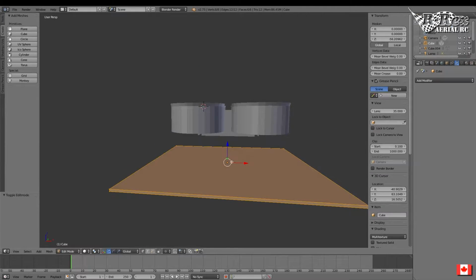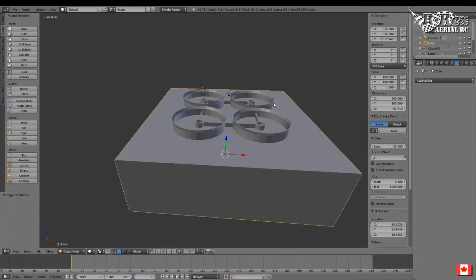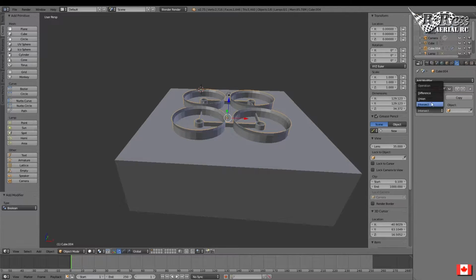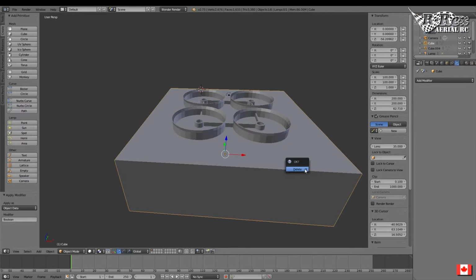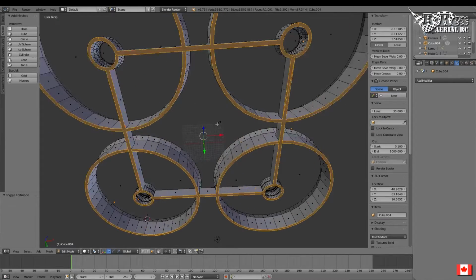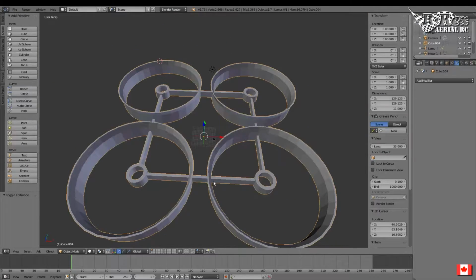Go into tab mode. Select the upper face. And I'm going to put that face to 5.5. There. You notice it consumes quite a bit of the object. So now I select the object, Boolean, difference, and select the cube, apply, and we can delete this cube now. Now, this object is perfectly flat in the best way. There's no stray vertices, there's no nothing. We now have the basic frame.